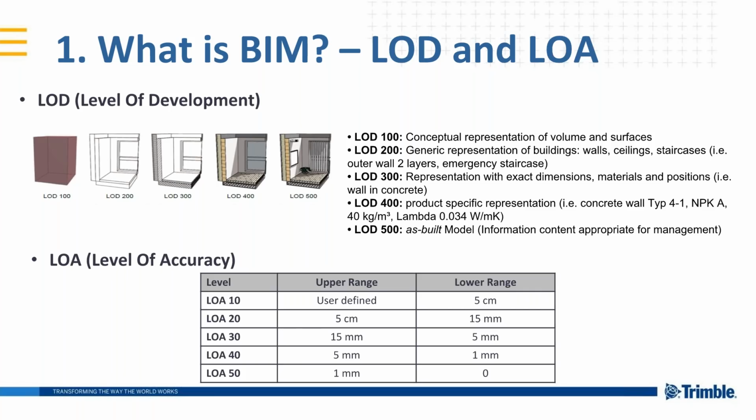Exactly. So also depending on the project, as I said, in some cases LOD 200 is enough, but in most of the cases, in many countries, you have to help your architect, your customer to decide which level of detail, because obviously ourselves as surveyors cannot provide LOD 400 or 500 with materials, with energetic values, etc. So depending on that is the time that we will require for the model and for the 3D modeling, etc. So these two points are key factors for you to calculate your time.